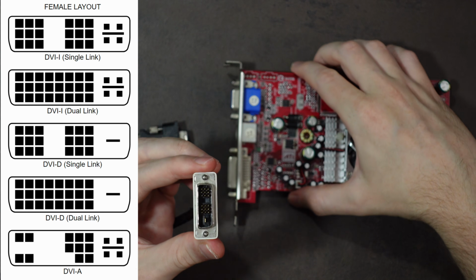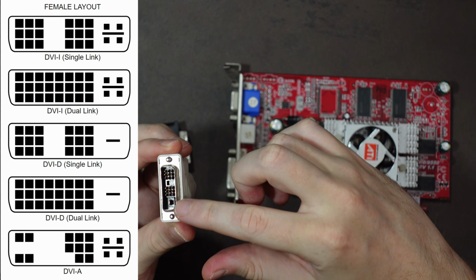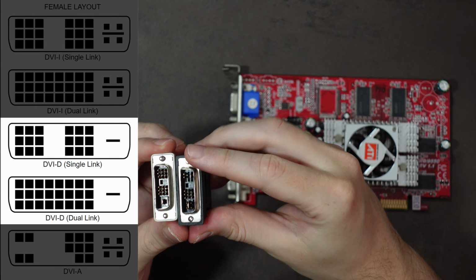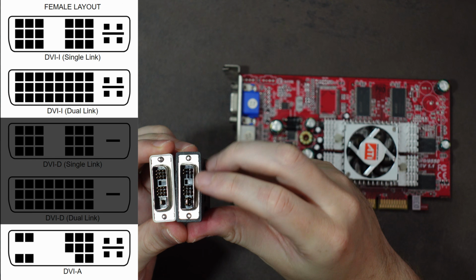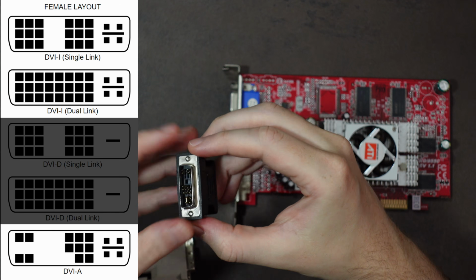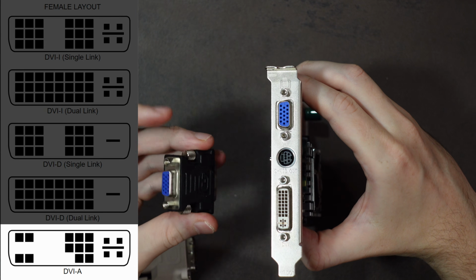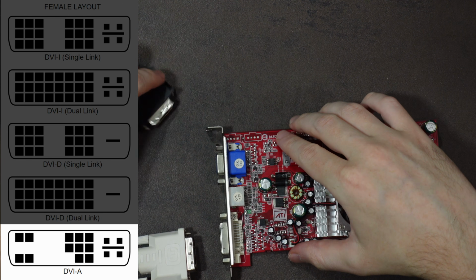You can easily identify the support for analog signals by checking the white pin on the right side. If it is standing alone, then the connection can only accept or send digital signals. If there are two additional pins above and below, it will also support analog signals, or only analog signals. But DVI which can only handle analog is rare and can mostly be found on adapters.